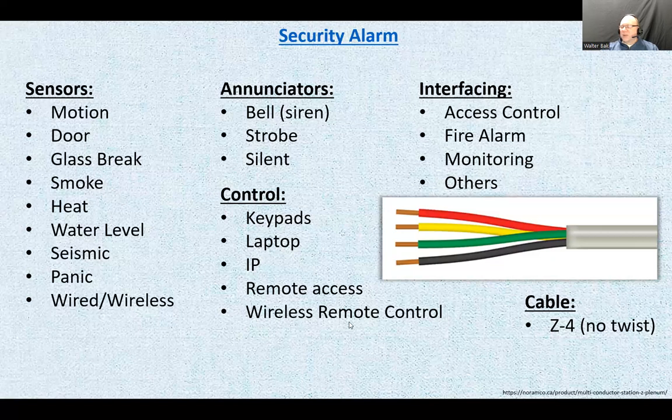All these could be associated with the programming and setting things up. This one here could be just a remote control for the user. Yes, the alarm systems can have a remote control. It's quite a useful device because you can have that alarm system programmed in something that's called a stay mode. Just like you're staying somewhere, it's called a stay mode. Some of the sensors, like the outside perimeter sensors, like the door contacts, the window contacts, and everything that separates the inside from the outside, could be armed for the night. However, all the inside sensors, like inside motion sensors and whatnot, could be programmed so when the system is armed in a stay mode, they are not active.